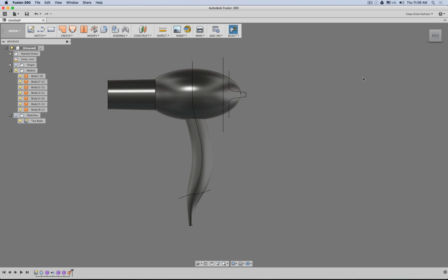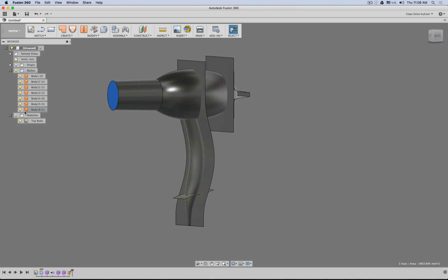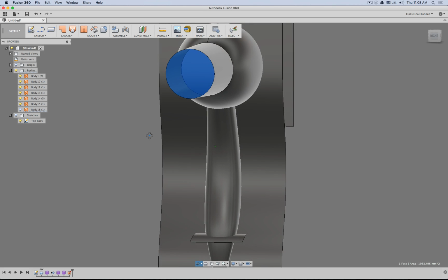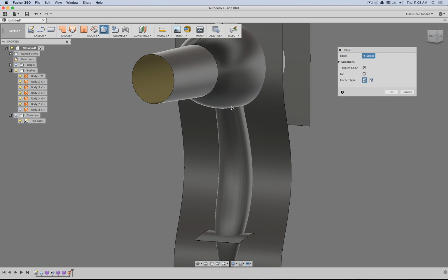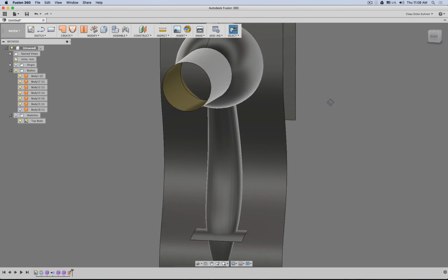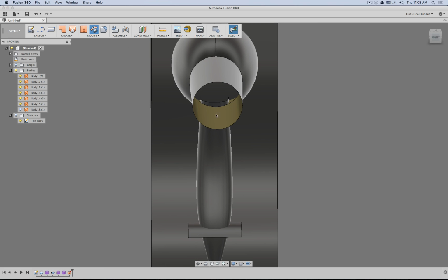Great. So I have the splitting, and the splitting goes through the body and the handle. But between body and handle I want to make a transition, so it makes sense, before I do this, to build the blend surface. There's something else yet to click because I haven't trimmed anything.